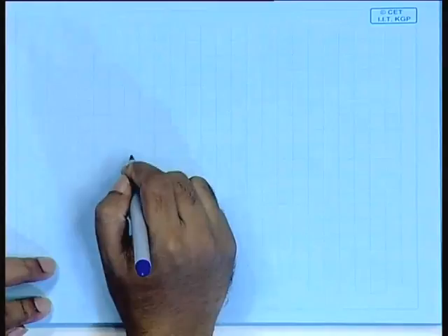It is going to give you the pointer to the function node which represents the AND of those two functions, but the BDDs for f and g are still there in that structure. So, are you getting what I am saying? See, there is one structure that it is going to use, right.